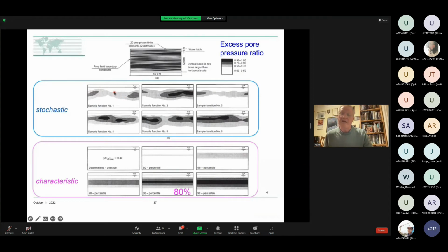So here we've rolled the dice once, rolled the dice again, rolled the dice again. And we've then run a standard earthquake against them with a cyclic liquefaction model. The color coding is shown on there. That's the RU value. So when we put the standard liquefaction test here, we get this much pore pressure. Over here with this realization, we get a lot more liquefaction, or a lot more pore pressures, and it varies from roll of the dice to roll of the dice.